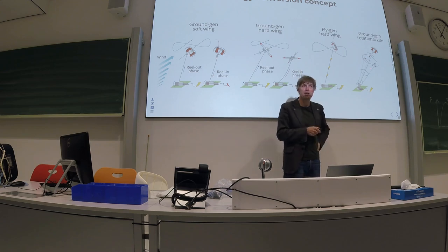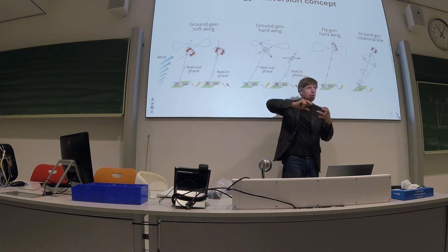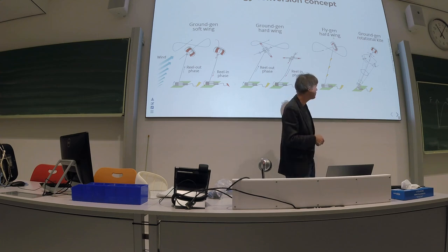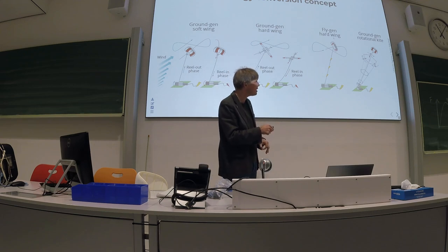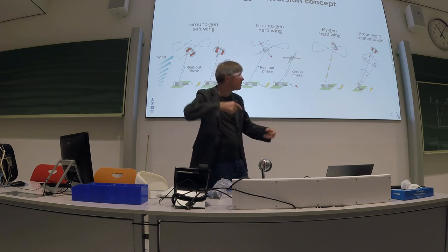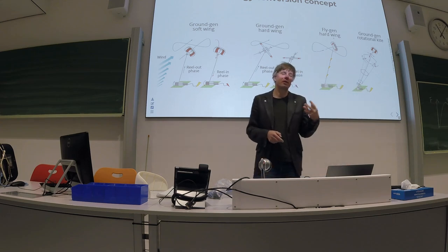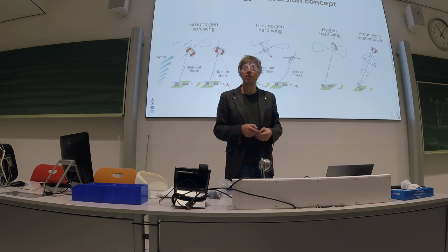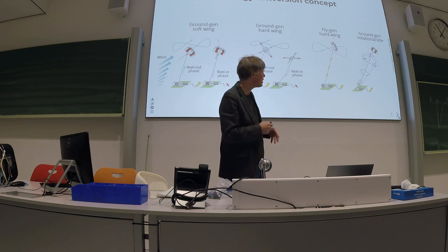It's basically a flying wind turbine rotor, and that rotor drives a networked tensile axis, you could say. These elements here are rigid, and they make sure that the tethers stay in place, but this whole tensile construction actually rotates and it drives the generator here on the ground. And this kite up here has the function to provide additional lift to get this whole array of this rotating chain into the air.